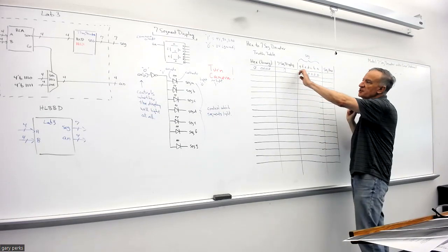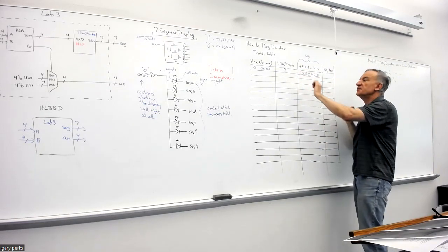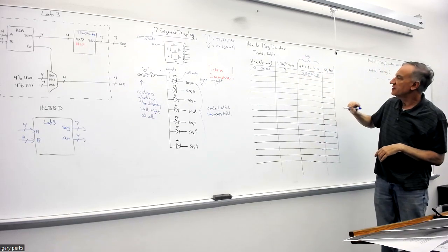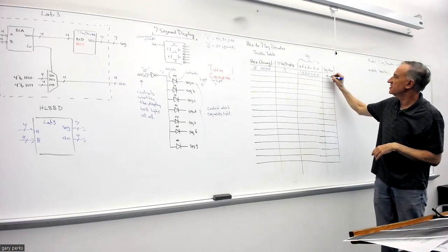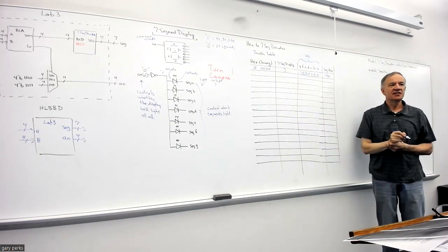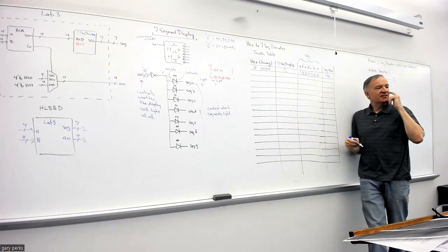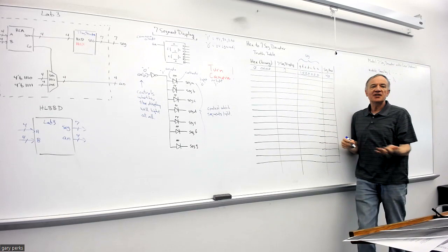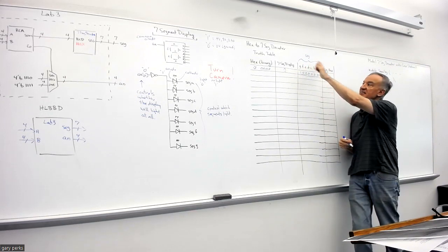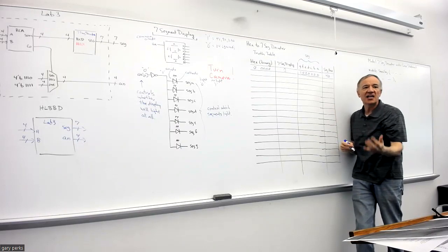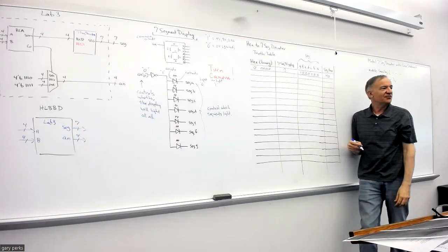Then you put an imaginary 0 here, so 0 1 0 0 is 4, and 0 0 0 0 is 0. So this would be 40 hex. Again, the convenience of hex in the digital world is that I don't have to say as much. Instead of saying the seg output is 1 0 0 0 0 0 0, I can just say it's 40 hex.